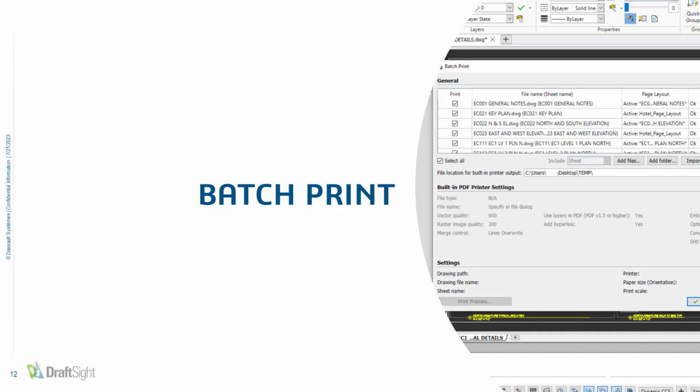So starting to wrap up here with number 9, we have the batch print capability. So I saved this for after Sheet Set Manager because you can actually batch print from the Sheet Set Manager directly, whether it's the entire sheet set or certain subsets of the sheet set. You also have the option to batch print manually from your hard drive or wherever you're working out of. However, the integration right into the Sheet Set Manager is an interesting extra layer into batch print capabilities. So I'm going to show you that right now.